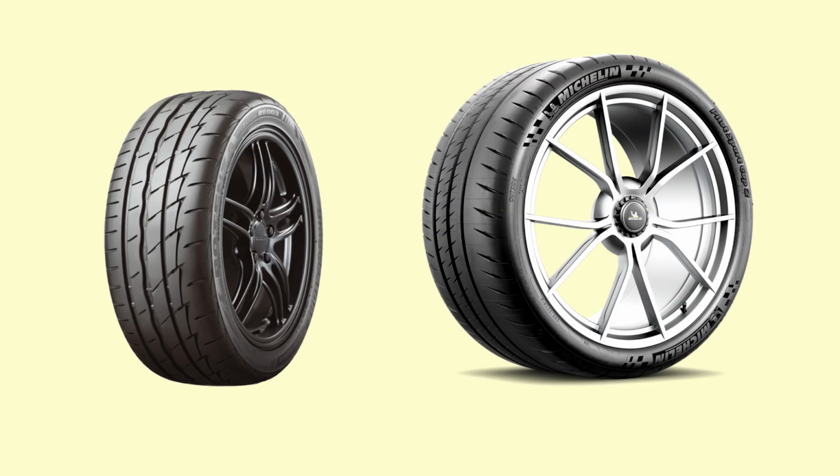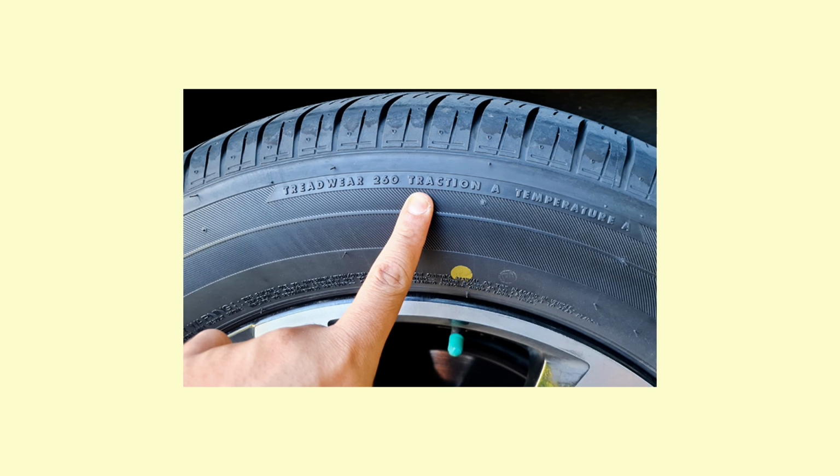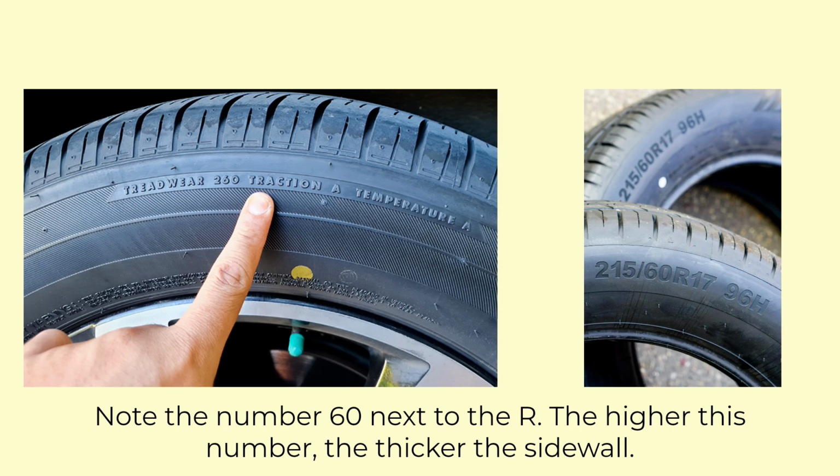Of course, upgrading to performance tyres is one of the easiest ways to improve grip and reduce understeer, especially with front-heavy FF cars. Many commuter cars from stock run higher tread tyres, which mean they last longer. They also have thicker sidewalls which cause less grip and stability when entering a corner, inducing these dreaded understeer characteristics.